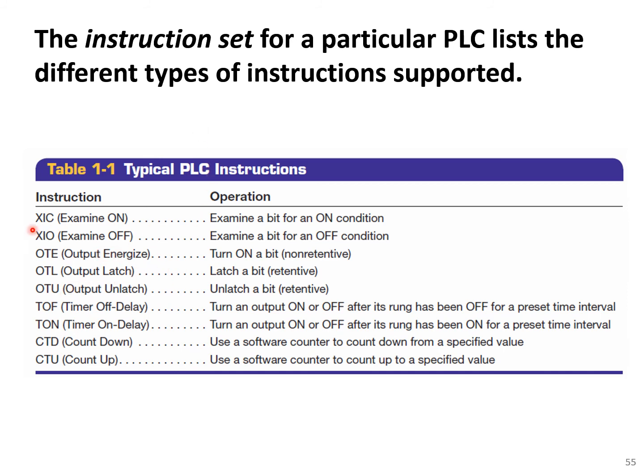Okay, so here we have some XIC, examine on, or XIO, examine off, OTE, output energize, output latch, timer off delay, timer on delay, count down, count up. We'll discuss these instructions in coming lectures, don't worry about that. But for the purpose of this slide, we want to say that not all PLCs will support all types of PLC instructions, and that would be a factor in choosing our PLC.